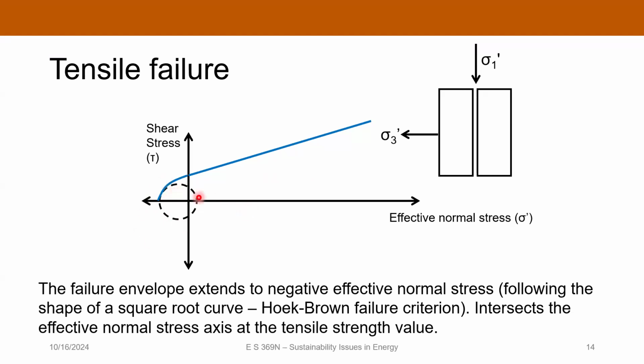But it's generally not going to be the case that... well, actually, this is an interesting point. If you're designing a hydraulic fracture stimulation and you've got a large difference between sigma 1 and sigma 3, you're going to have a hard time not just inducing shear failure around the wellbore. That can be a bad thing, because shear failure is going to behave differently than tensile failure when you're stimulating that well. So there are certain states of stress where fracking just does not work as well because of that phenomenon. Just an interesting thing to ponder.